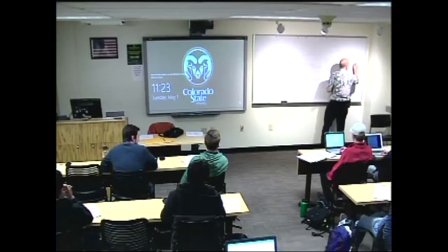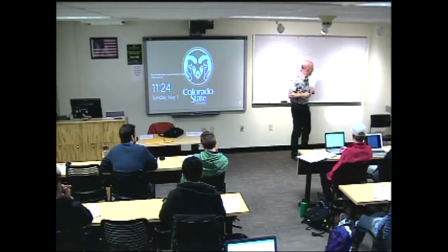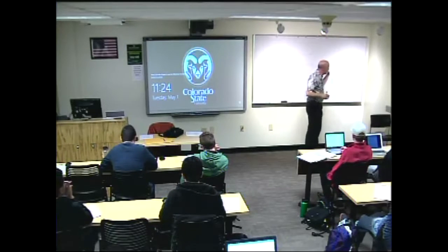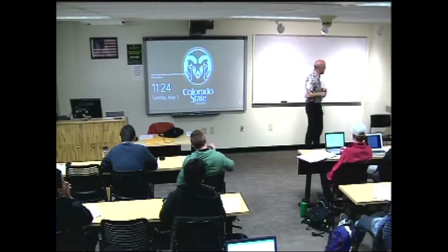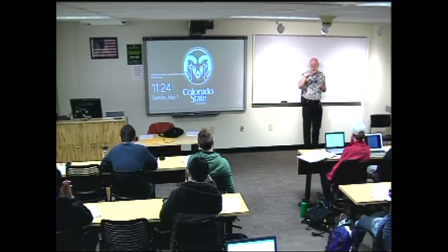I should have probably called this V out, but I labeled it as VC. Those are the same thing. And you figure out basically how low of a bandwidth of a filter you can use without messing up the time constants of the signal by any more than 1%.